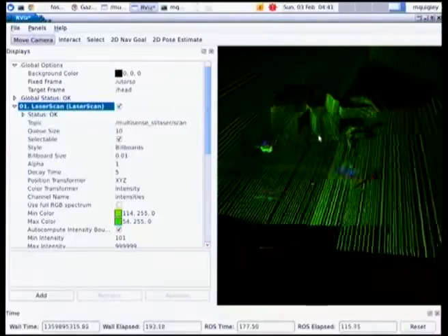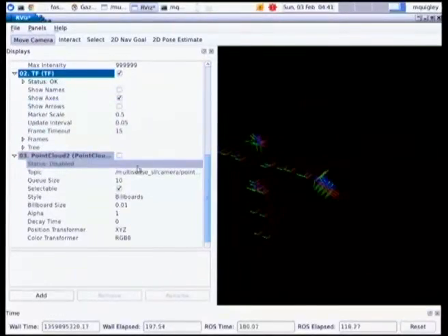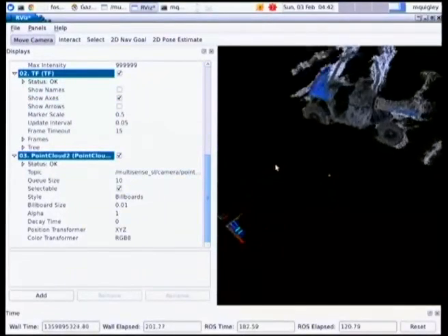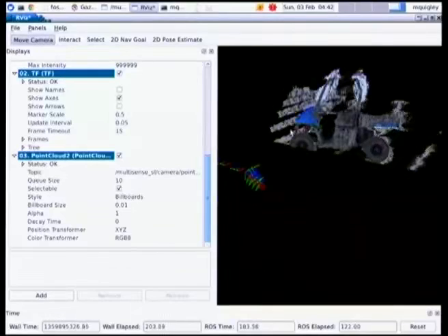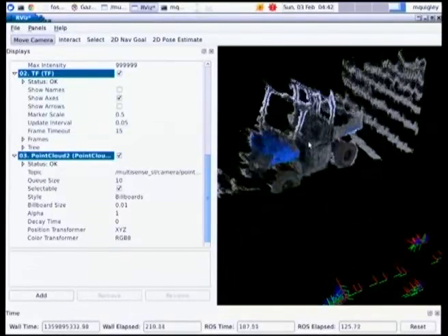Okay, so we have pictures. We can then run the stereo pipeline just like a normal robot that actually has cameras. So this is actually what the stereo pipeline is computing. Now this is important to note. This is not just a point cloud that we're generating from the simulator. We're actually generating images and then running stereo vision on those generated images.